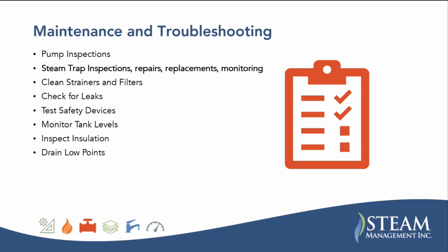That's one way to verify condensate flow. We've assessed opportunities by measuring just tank levels over time and calculating flow that way. So when you don't have a condensate flow meter, those tank level gauges are your friend as far as getting a picture into what's going on there.